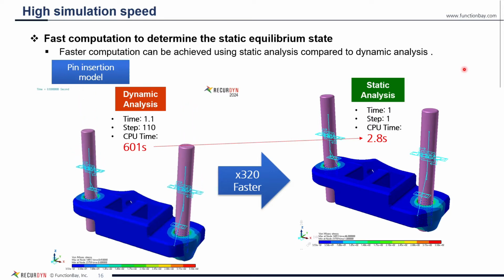In dynamic models, applying large stiffness values can be challenging because they can reduce the step size, resulting in long computational time. However, in static analysis, inputting a large stiffness value does not significantly affect convergence. This can sometimes result in more accurate outcomes.